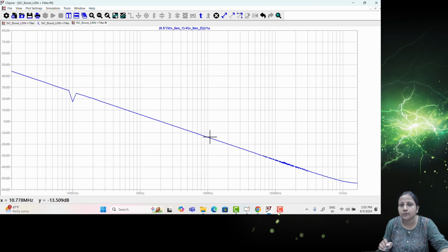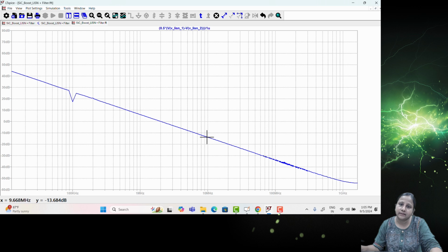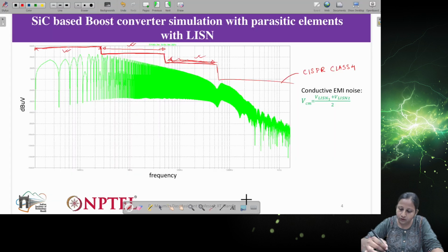There is no problem. But sometimes it will happen that if you design the filter for high frequency, it may not satisfy the requirement of low frequency attenuation. So you have to check based on your application. In some applications there is variation in control frequency, but in others there is not. If frequency variation is there, you have to choose different stages in frequency to design the filter. If frequency is constant, you choose only a single frequency to design the filter, and then you can get the actual value.